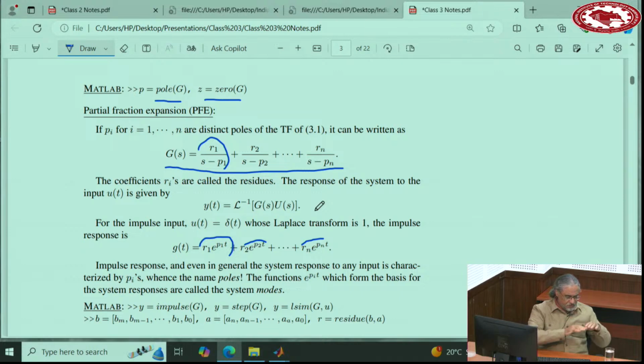If the response of a system can remain bounded, we say this system is stable. If it grows and goes to infinity, we say this system is unstable. So immediately you see the condition. We can mathematically prove all the details, but it's not necessary. So the condition is all the poles must be on the left side of the complex plane. If they have that condition, the outputs of this system remain bounded for every bounded input. So as long as the input is bounded, the output is also bounded.